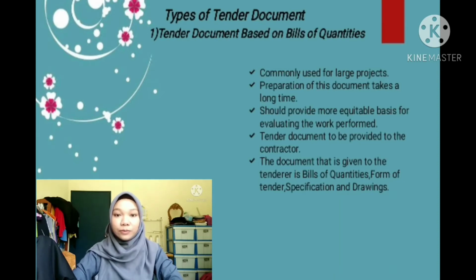The tender document to be provided to the contractor is subject to the type of contract offered. If this contract is based on BQ, the documents given to the tenderer are the BQ, form of tender, specification, and drawings.